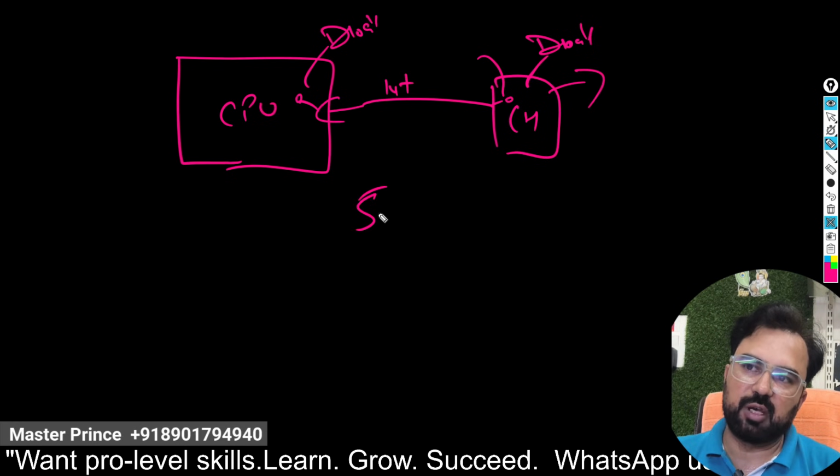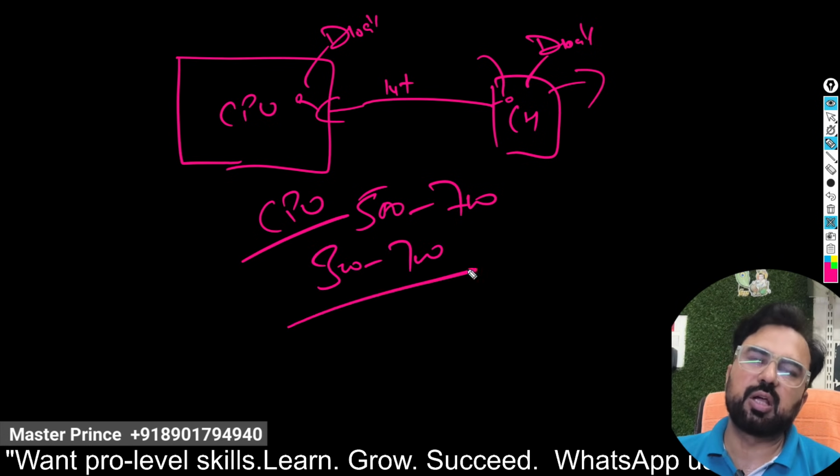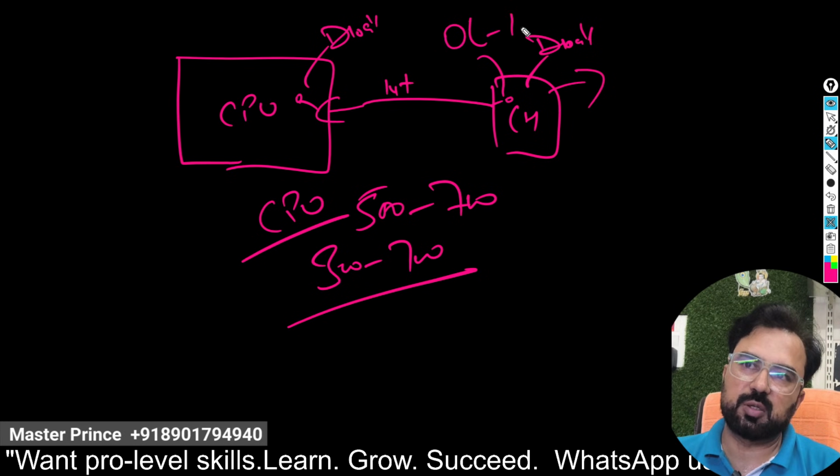If you get a diode value, let's say from 500 to 700, this diode value belongs to the CPU, let's say 300 to 700 depending on the multimeter, that means your CPU is connected. If this line shows OL or a 1000 plus reading, that means this line is disconnected. In that scenario you have to connect a jumper under the IC.